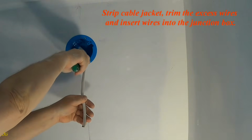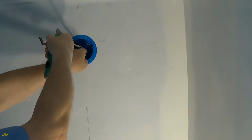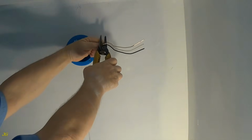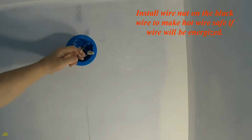Strip the cable jacket. Trim the excess wires and insert the wires into the junction box. Install a wire nut on the black wire to make the hot wire safe if the wire will be energized.